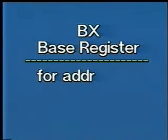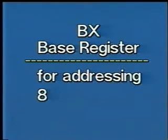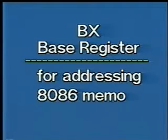BX is called the base register. This is the only GPR whose contents can be used for addressing 8086 memory. In fact, 8086 BH and BL registers are equivalent to 8085 H and L respectively.